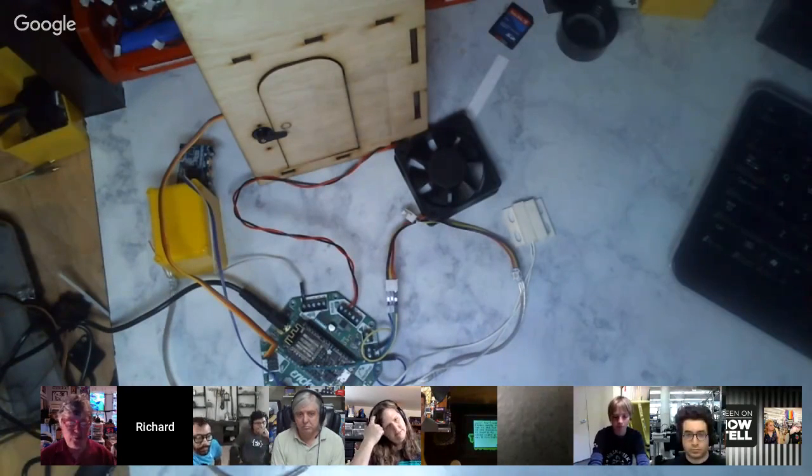Hey guys, so I wanted to show off a project I've been working on. I've shown off my mini smart home with the micro:bit. So this is the newer version with the Cricket feather wing, and using the Huzzah ESP8266 chip. I have this running MQTT, but it's not running through Adafruit IO. It's running through a local server. So this is all running locally. It's not even touching the internet for anything. You can port forward MQTT to do that.